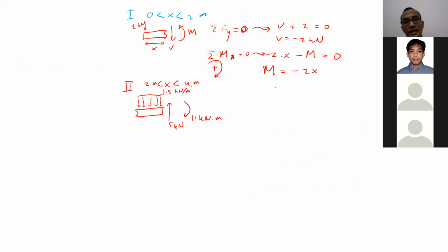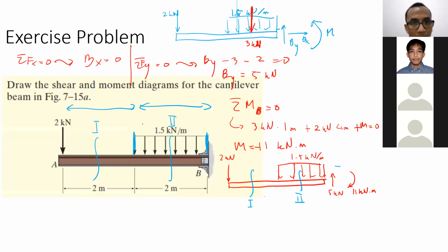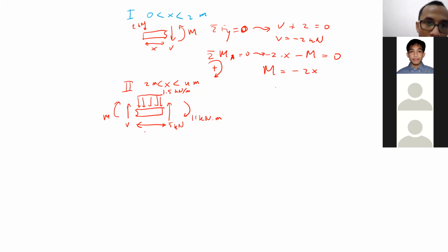At the cut there, what will we have, Safran? Shear force upward, correct, because it's positive clockwise, and then moment clockwise, right? And the distance is supposed to be what? 4 minus x, correct. 4 meters minus x, so 4 minus x is our distance.